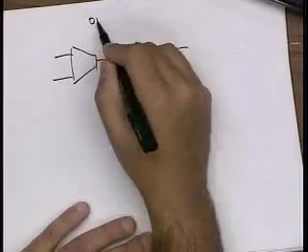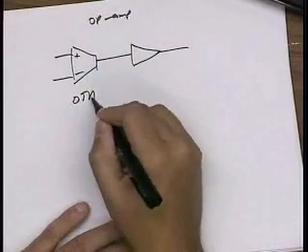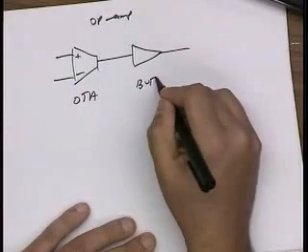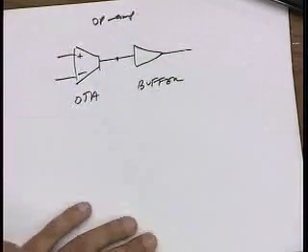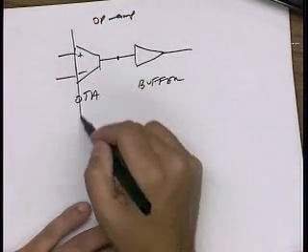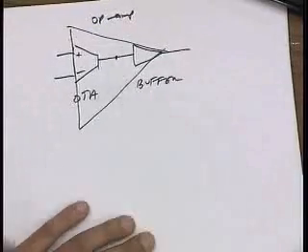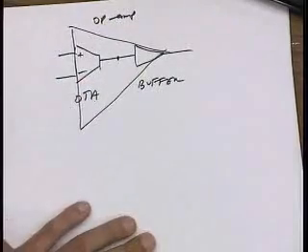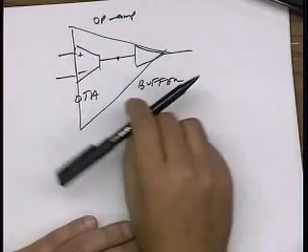So this is actually an op-amp. It has an OTA, and then it has a buffer. That buffers my high impedance point to a low impedance point. So really, this is an op-amp, and if I chop off the end of an op-amp, I get an OTA. So really, the symbol has a lot of analogy to it.